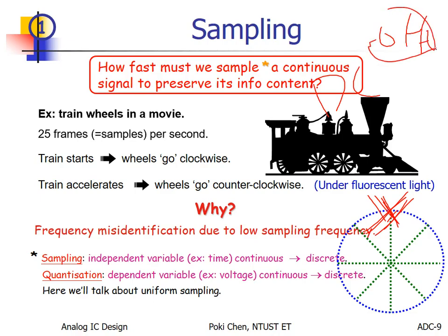So if you only sample once per cycle, because of the Nyquist rate, you need to sample at least 2 times per cycle. But right now, your frequency is 2 times higher than that. So you miss this. You don't have that one. You only have this.